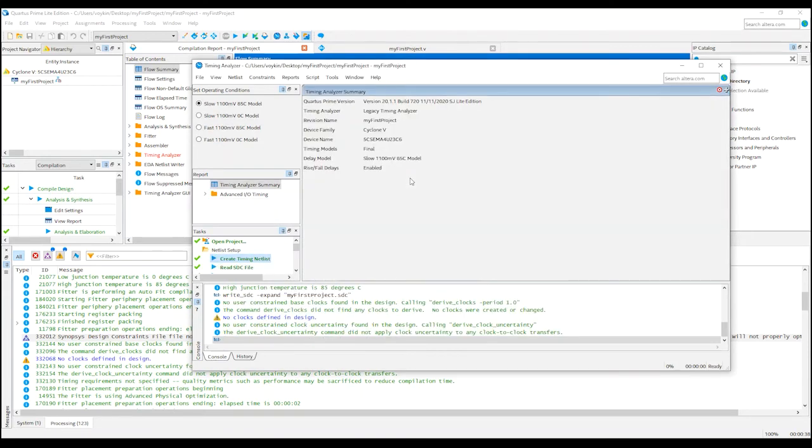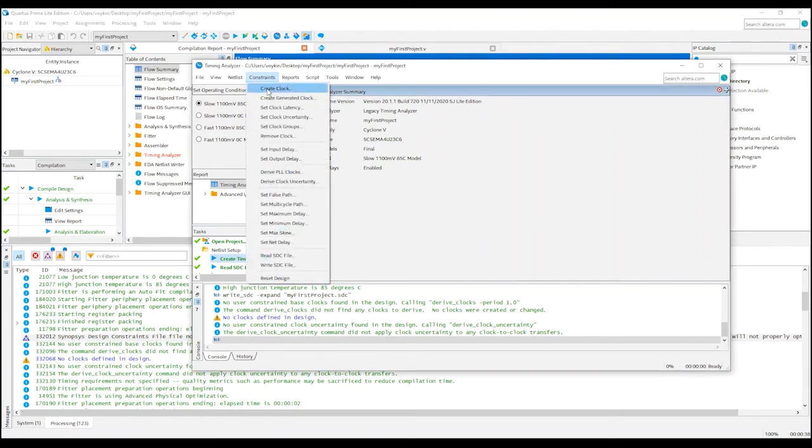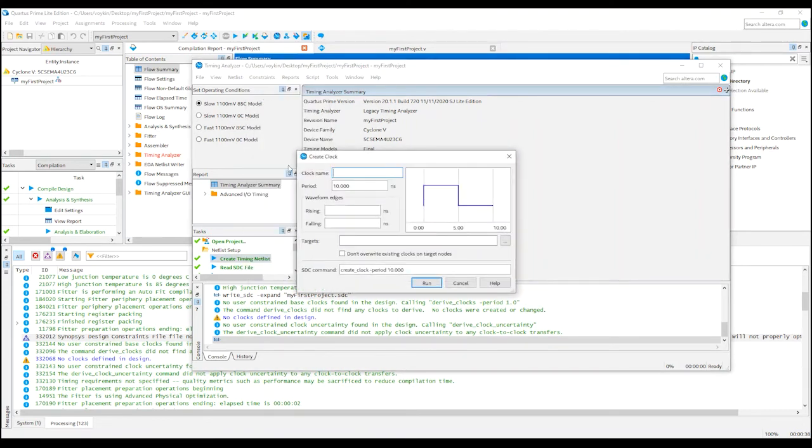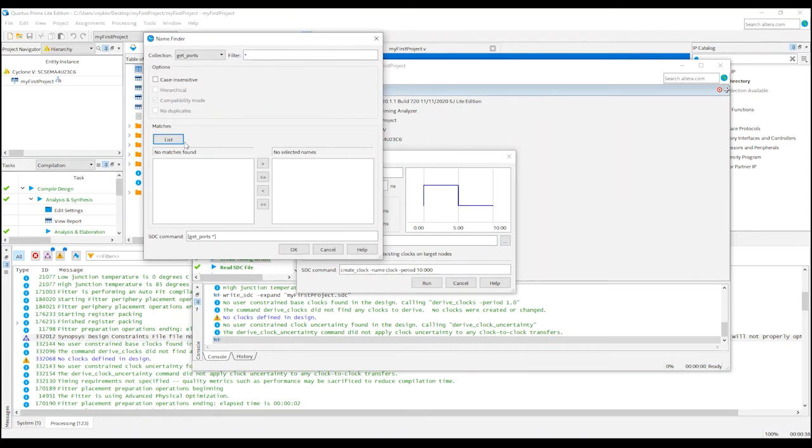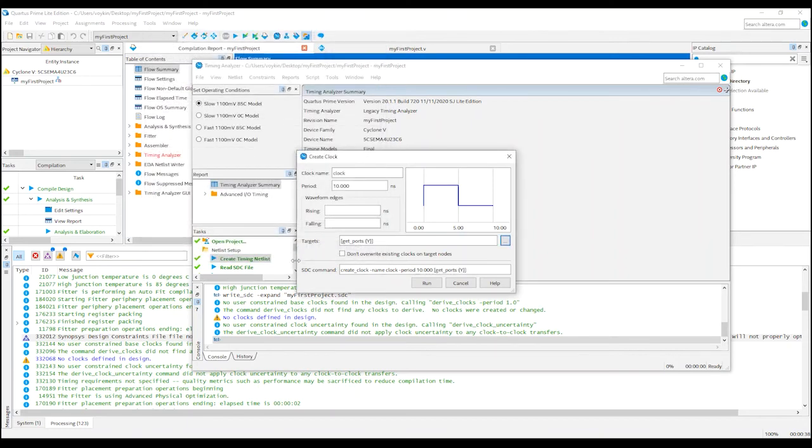In the next step, we're going to create a clock for the design. Now, our example is very simple and doesn't contain any flip-flops, but most FPGA designs will have flip-flops. So, by default, every FPGA design will require some sort of clock assignment. We're going to add that clock assignment to our SDC file now. You'll notice that we stuck with the default period for this clock.